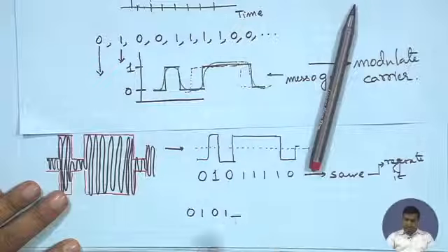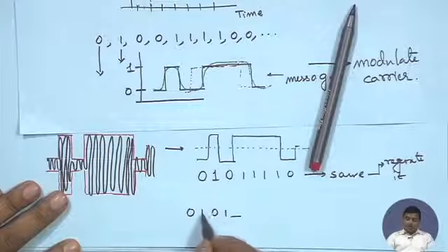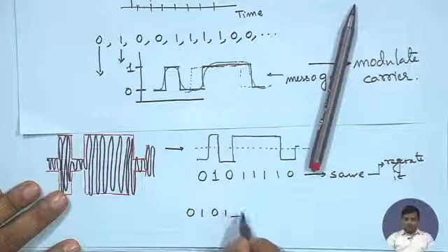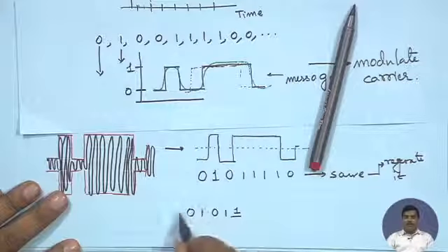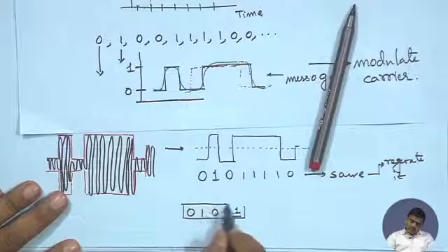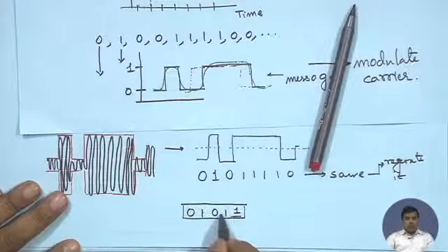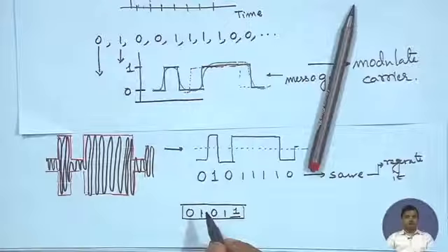When I say I want to have an odd parity, I am going to have one extra bit over here, which will be used to complete the parity to make it odd parity. So as of now I have 2 1s. If I put one more 1, I am going to get 3 1s. So I will know whenever I receive 5 bits, 1, 2, 3, 4, 5, the sum of 1s should be odd.